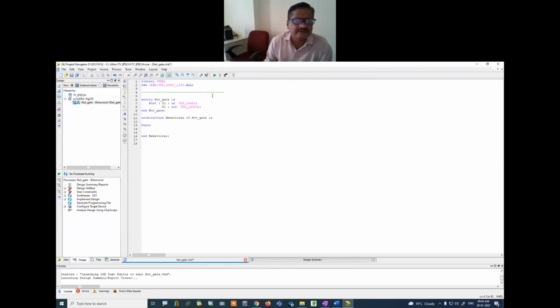Is it right? Means I'm able to separate the things. This is the library declaration part. I'm using this hyphen comment to separate between the modules. It is not necessary, but I'm showing it to you here. First, this part is the library declaration. This part is the entity declaration. This will be created directly by the system. I'm not doing anything for this. It gets created automatically.